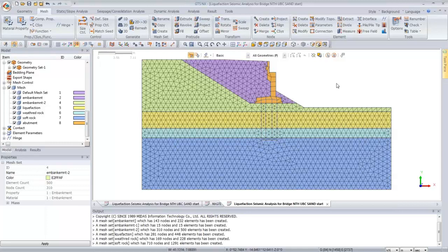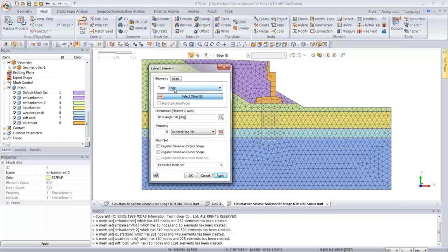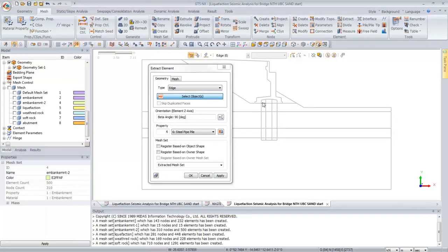So now we have the 2D meshing complete, and we can proceed on to mesh the piles. In this case, I can either just mesh directly 1D or extract the element, which is also common practice if you're doing some sort of excavation model. And we can do it directly from selecting geometries, edges. So here in the workstream, to make this a little easier, I'll deactivate the things that have already been meshed and leave only the geometry so I can extract the piles easier.